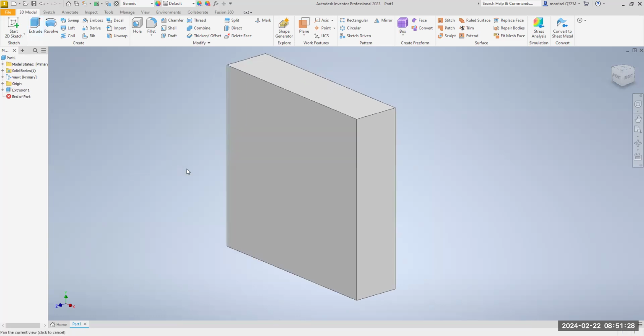All right, now that is the general shape of our block. Now we're going to do some milling on this block. If you look at the picture, we actually do a profile mill around this, and we take off 1/8 of an inch all the way around the block. In this case, it's going to be 1/2 of the milling tool, the milling cutter. So here we go.